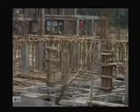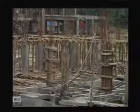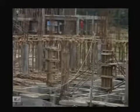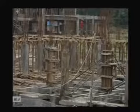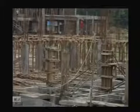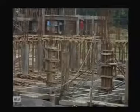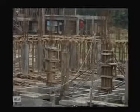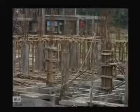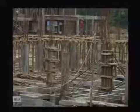And I have already told you about curing. Curing is generally done like this: with jute bags and all those things, we just cover it and we put water, and that is actually called curing. And we have to do that curing also, that is very, very important. Even if you cast it properly, with all the care you have taken, even then you will not achieve the target strength for which it is designed if the curing is not done properly. So that is very, very important.